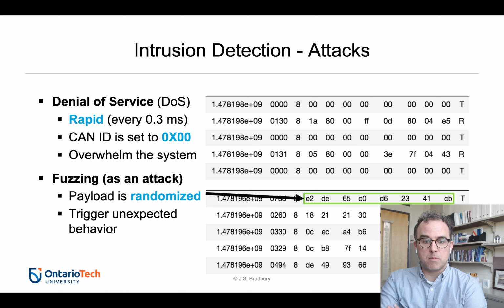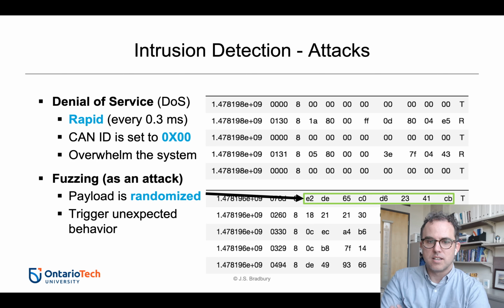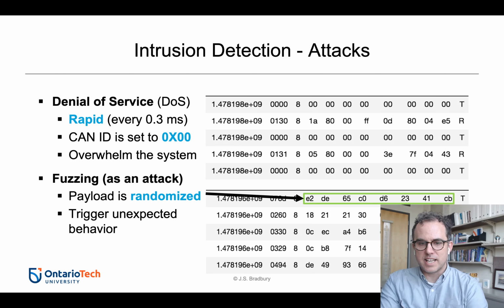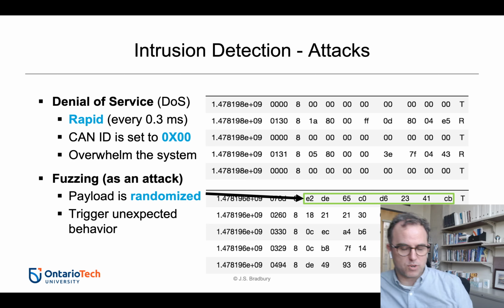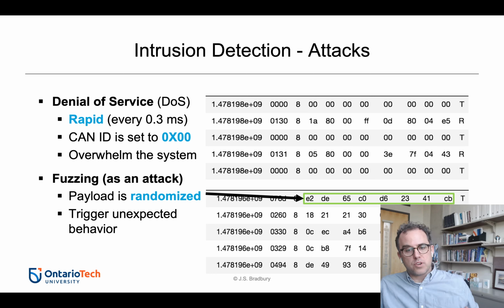And then there are other types of attacks too, which can be more nefarious. Even further, if I know what a certain ID message is and I know it's related to a certain behavior, I could actually target a certain message ID type with certain data. For example, I could take real data, decode it, get the signals, change a signal, re-encode it, and pass that along to give it real incorrect data. So for example, if there's a message about an object, a car in front of them, I could adjust the distance by doubling the distance, or making it think the car is twice as close, so it slams on its brakes, or those kinds of things, which is obviously not good, and that's what we're trying to prevent in our case. So these are examples of some of the attacks that can happen.